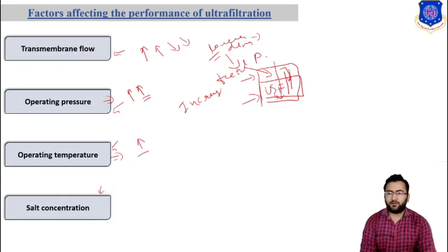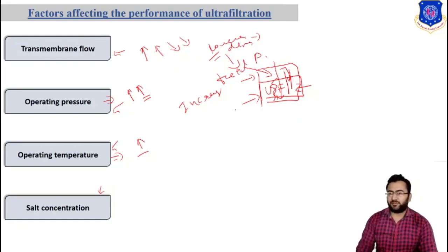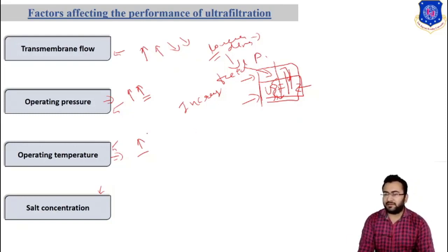But if we increase the temperature beyond the critical temperature for this ultrafiltration membrane, there will be a chance of cracking in the membrane, and it will fail during the process. So it is necessary to run this ultrafiltration process at optimum conditions.